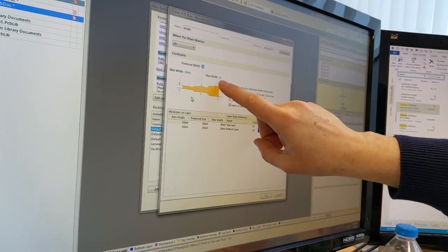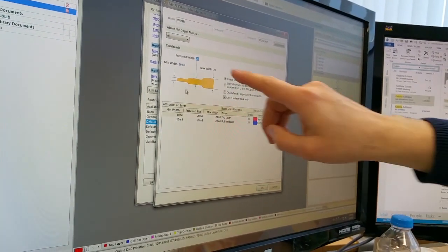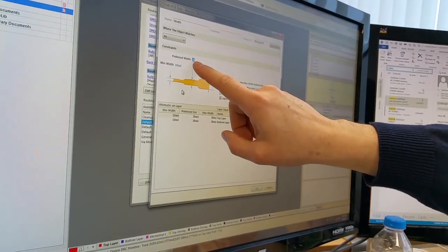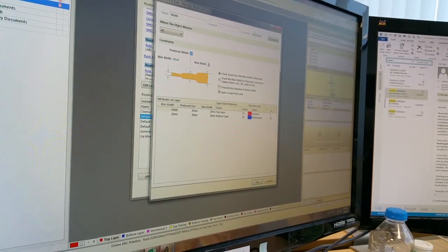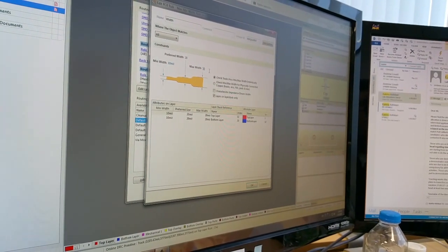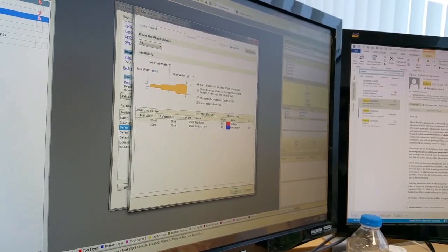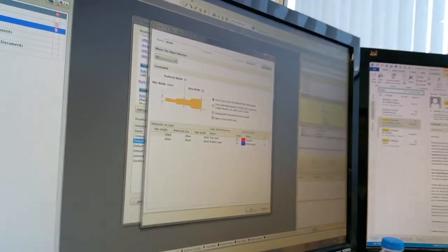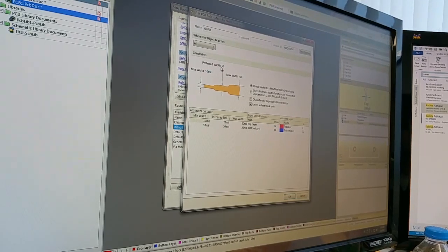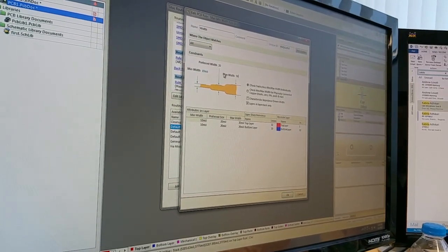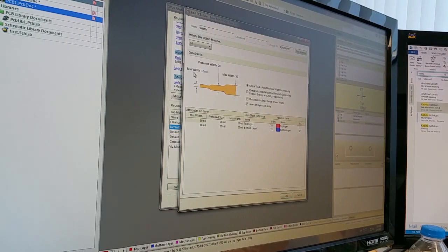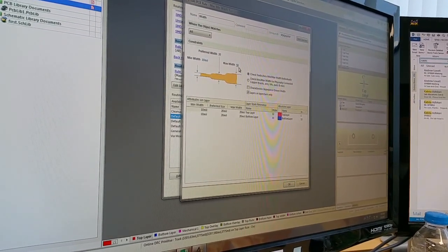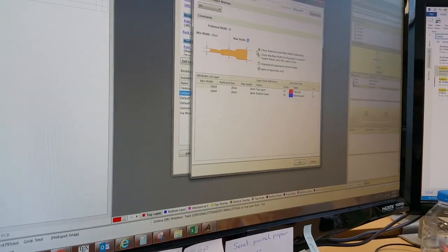So how does the package use this size? The package will use the preferred width. You tell it the preferred width will be, let's say, the maximum, 50. If there is no way to do the preferred width, the auto routing goes smaller and smaller. So the auto routing will look at the preferred one first. If there is no space, it goes to smaller, the other options. And if it's possible, it will sometimes choose the larger, depending on the area of the PCB.